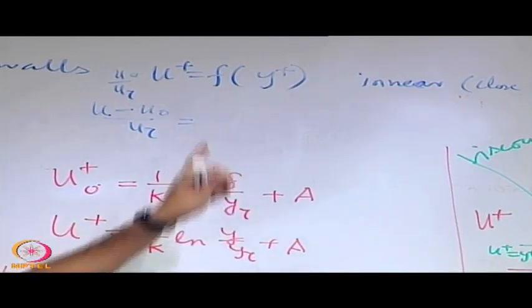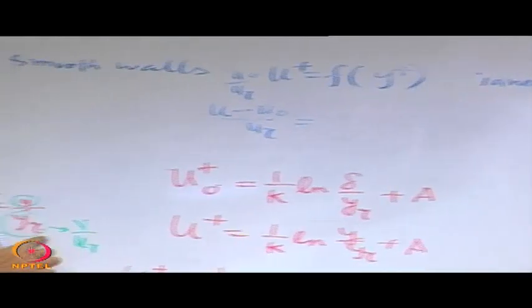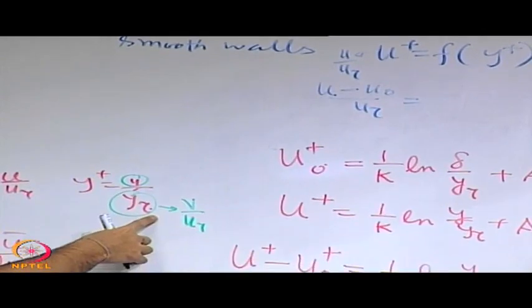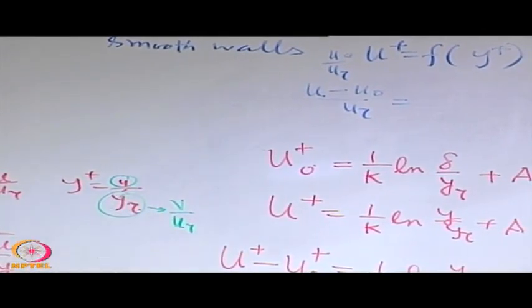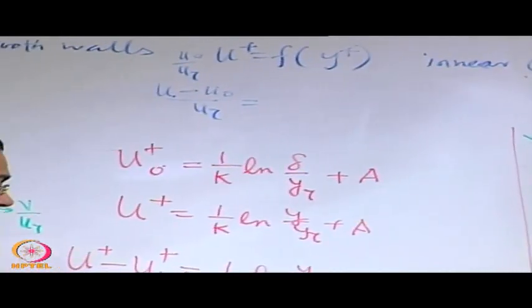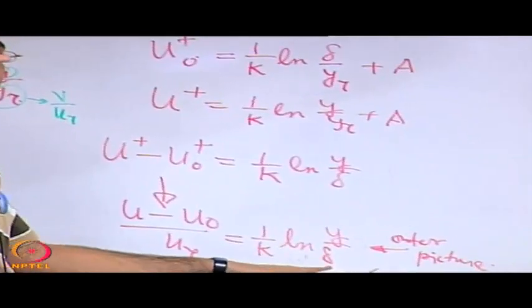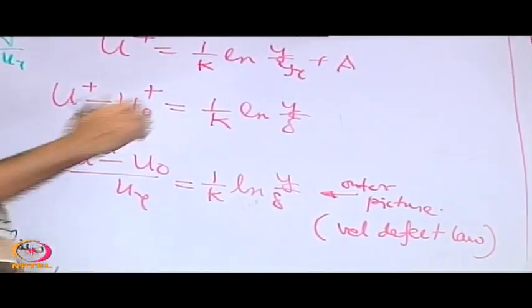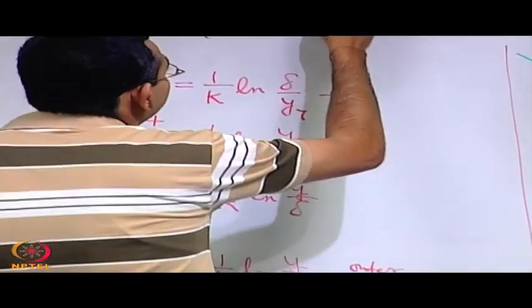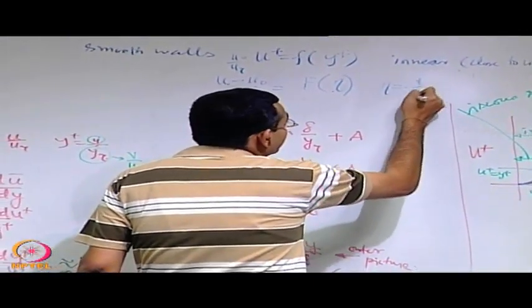The important thing is that y plus is dominated by a viscous length scale, a length scale based on the kinematic viscosity. As you go in the outer region, the velocity profile is governed by y and the system length scale, but not nu. So this is another function of, let us call it eta, where eta is equal to y by delta.